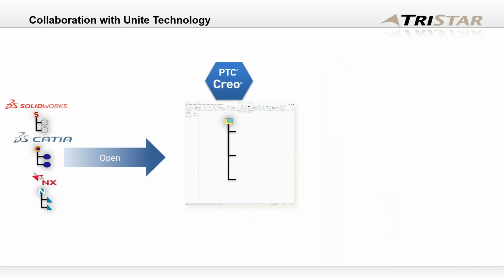Now, collaboration is more like, you may be importing all these SolidWorks, NX and CATIA files into Creo, or opening, I should say. But then you're doing your cross-platform design intent where you keep adding geometries or you edit some geometry using geometry edit features. You're building some references or relationships in the Creo assembly using this multi-CAD data. What happens if that original source data gets changed in the source CAD system? Say a week from now, they send an updated SolidWorks file that I am using. Now I'm supposed to be using that. You don't have to undo everything and redo.